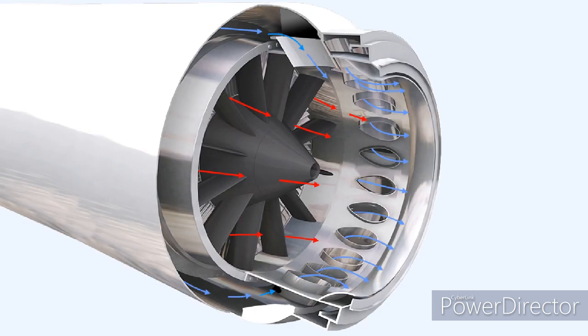Having two gas streams to pass to atmosphere makes the exhaust system of the bypass engine a slightly more complex affair to the essentially simple systems we've examined so far. The low-ratio bypass engine exhaust shown here combines the bypass air and the hot exhaust gases in a mixer unit. The mixer unit ensures thorough mixing of the two streams before they're ejected into the atmosphere.